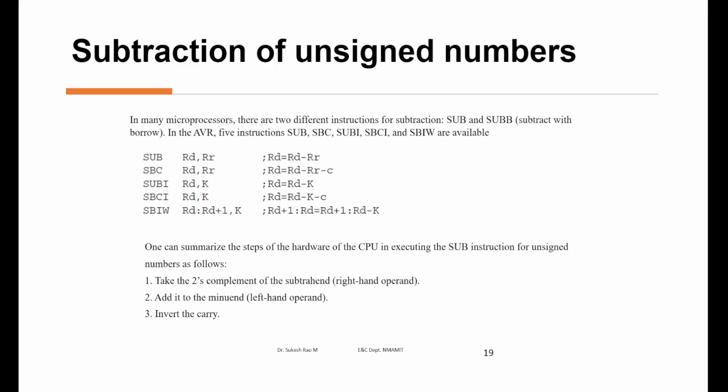Straightforward. This is SBC, which means subtracting the carry, which you call borrow. And you have SUBI, where you subtract a literal value from Rd minus K, and that is with borrow. And there is one more.